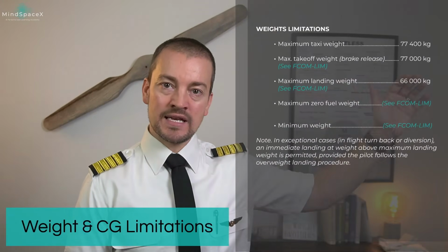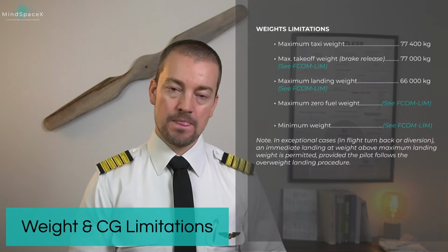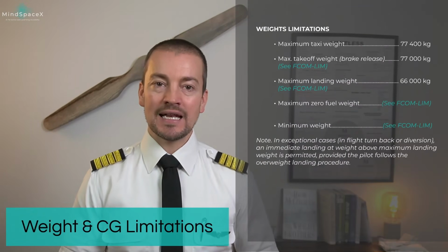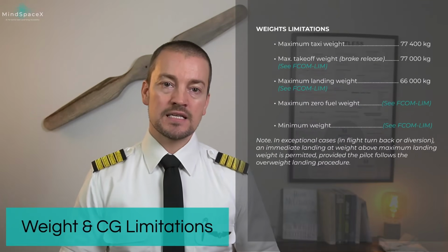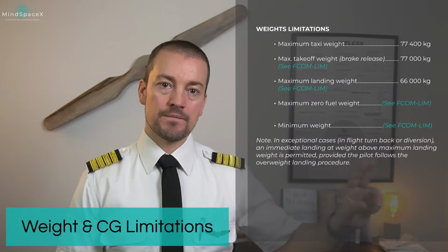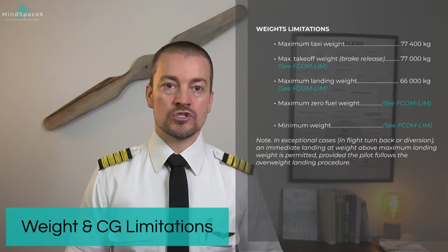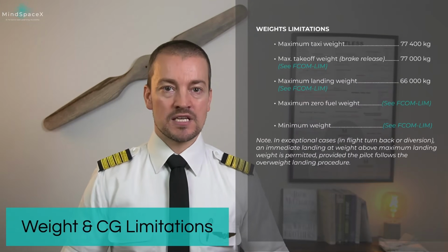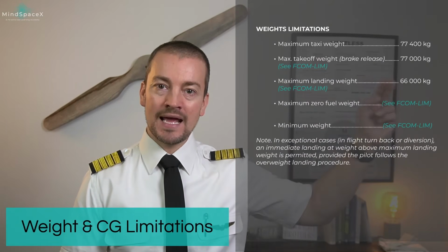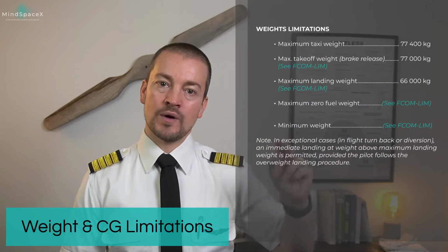Maximum landing weight in the aircraft I have listed here as 66,000 kilograms. I have listed it because at 66 tons, any landing above this is considered an overweight landing procedure. As it notes down here, in exceptional cases, in-flight turnbacks, diversions, immediate return back to the airport after takeoff, an immediate landing at a weight above the maximum landing weight is permitted, provided the pilots follow the overweight landing procedure.